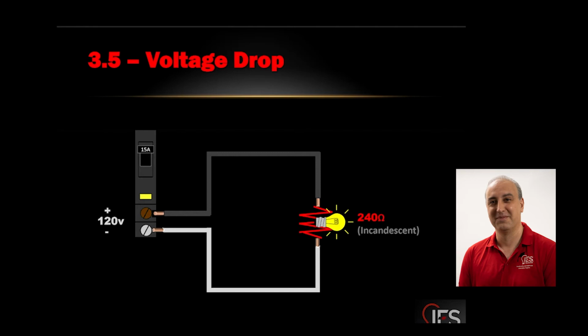Now, what you're saying, you see it in the field, because let's say you're wiring up a water heater or an AC unit. There's no neutral, no white. What happens is the two that you're bringing in, they're two hots or two ungrounded conductors. They're actually working in opposite phase. So when one is pushing, the other one's pulling. So that flipping is happening. It's just that it happens exactly the same time for both of them.